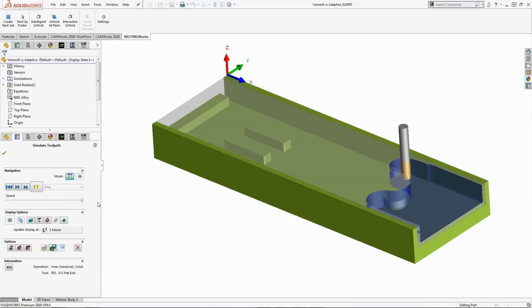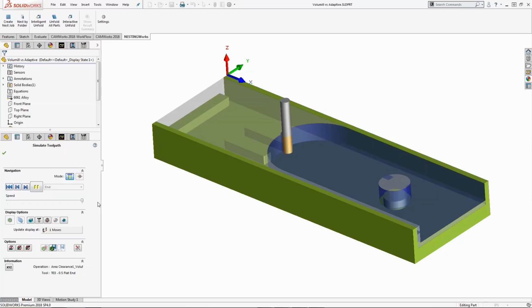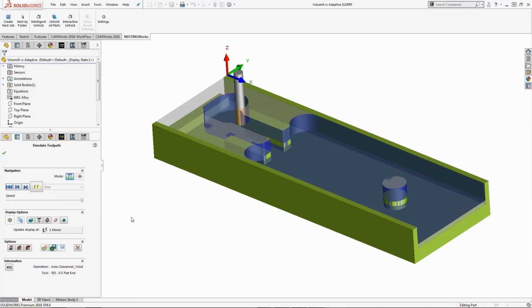This is where the advantage of the constant loading of the tool comes in. There's really no shock where there are interrupted cuts. It's always engaging material, and not only, number one, is it quieter, but number two, it'll extend tool life. And then, of course, when you have that factor in play, you're going to be saving tool costs because you're not going to be buying as many tools. So let me go ahead and pause that.